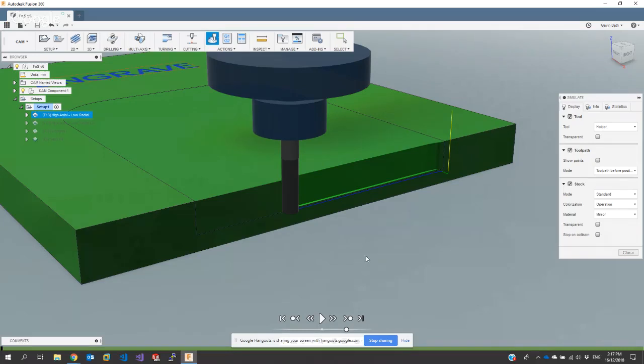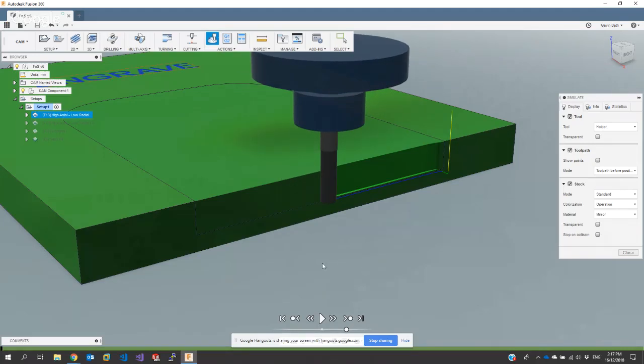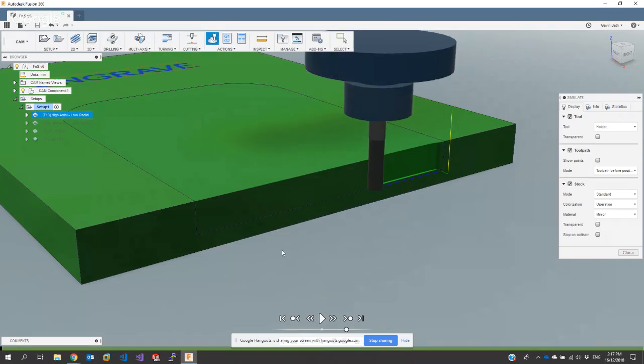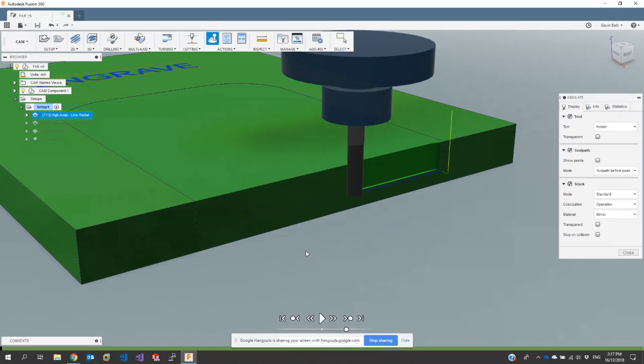Well, we have to ask a woodworker whether that's a thing or not. But generally, with manual machines where you turn handles to drive the axes, you usually avoid climb milling with any kind of significant load on the tool, because the tool can start to effectively drive the axis. The friction between the cutter and the tool will actually pull the table, and you can have it run away on you, and it's quite a scary thing.